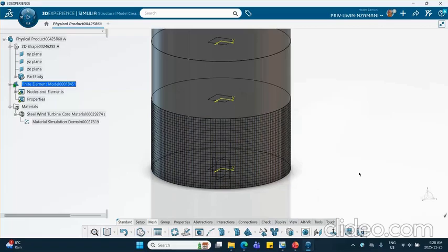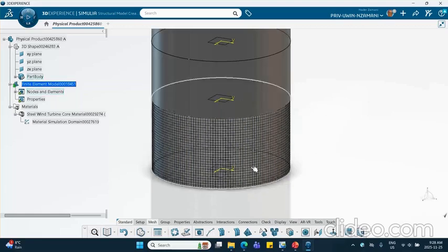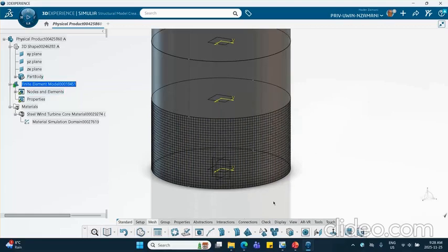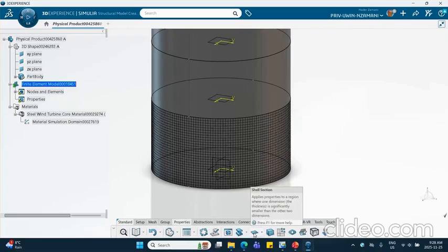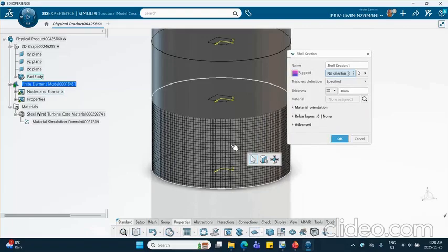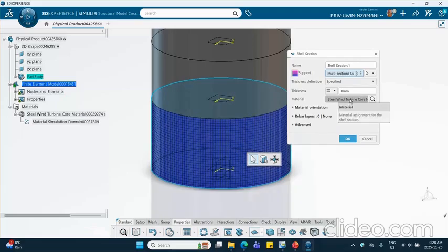Now, we can apply our section property right there or mesh all of these and come back and do it. I'd rather do it at the same time. I will do maybe 2 or 3 of these and then we come back, okay? So let me go ahead and go to properties. Here is section, shell section. You select this, automatically the proper material is selected, and this particular one has a thickness of 17 millimeter. If you go back to the slide, 17 millimeters, right? Say okay.